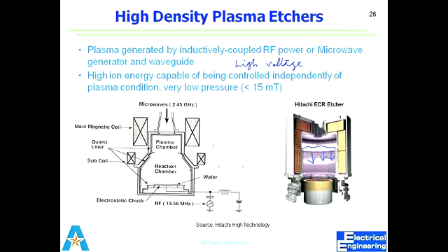After this is a film that I need to pattern. So what I do is, after masking, I try to etch this thing. Due to the isotropic etching, it will etch like this. If I continue the process, I'll get something like this. You agree with me? Okay, I don't want it like this, I want something like this. I don't want the lateral etching in that case.